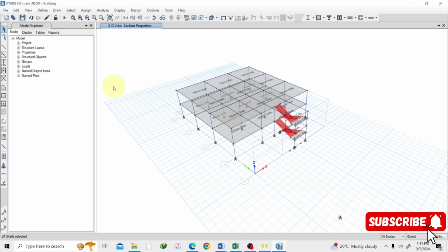The staircase is also a slab, so we are just going to assign a mesh. The mesh is not really a structural element, like when you say I'm placing a rebar into this slab, I'm placing reinforcement into this slab. It's not a structural element. It just makes the slab behave in a more realistic manner. As in, when it comes to the distribution of loads, the loads are distributed with some form of accuracy into the various supports, either the beam or the column. The distribution within the slab is very accurate. But when you don't mesh your slab, it's unable for the Etabs app to analyze this.